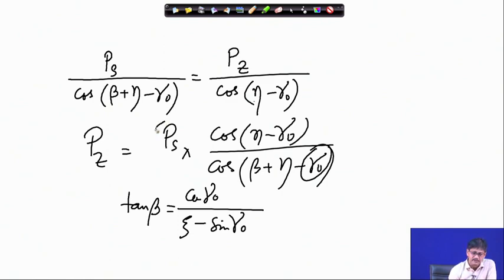Secondly, what is Ps? Do I have an estimate of Ps? If I assume that Ps must be equal to the stresses which are either equal to or crossing the shear strength of the material, then only failure must be occurring. So, if I multiply the shear strength of the material with the cross section which is undergoing the shear, then I might be able to find out the expression of Ps.